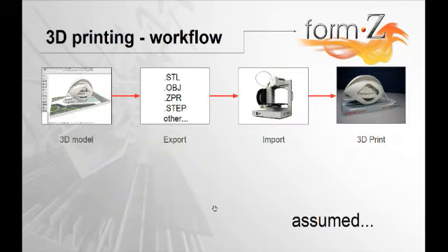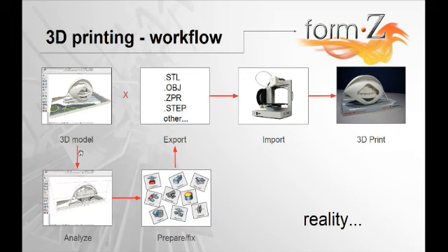But the thing that I want to talk about is, where does FormZ fit in with the 3D printing workflow? It's assumed that you take your 3D model, you export it out, the printer reads it in and prints it out. It's done, right? Well, actually, in reality, there's this extra little step that you have to do, and that is you really got to analyze that model and have the tools and features to prep it and fix any irregularities.